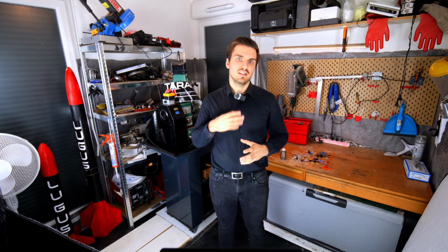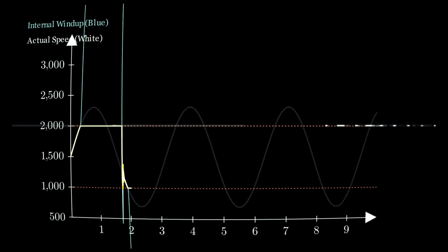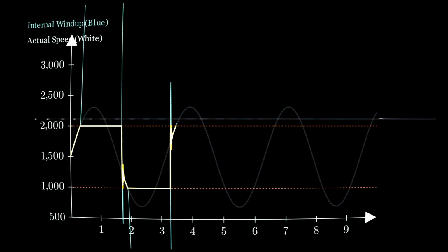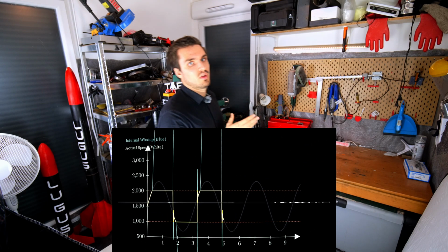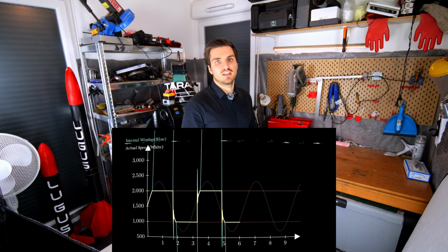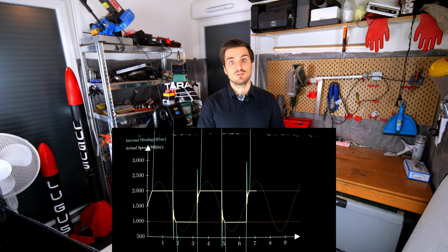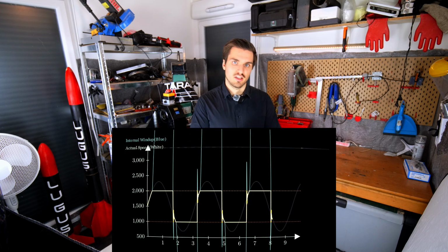Then when the value returns to the controllable range, the integral error is so large that the controller will simply order the motor to continue running at full speed. And the roll rate will simply cross the control range and start again on the other side, with a roll equal or greater than what we had before. That's the wind-up, and you will notice it's pretty silly. Basically, the integral just needs to calm down when we are saturated.